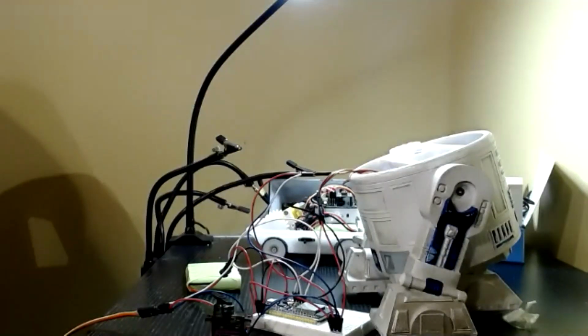Yeah, I've got a quick question. When I look up on Amazon, I see different variations of the ESP32. I see an ESP32S and an ESP32 CAM. What's the difference? What are we going for? Is it just strictly ESP32? The ESP32 is the main core chip, and then the ones that I got were dev boards. Now the pinouts, whereas your Arduino seem to have standard pinouts, and again, anybody who knows better just jump in, there doesn't seem to be the same standards on the ESP32s. But all I think it means is that you just have to make sure that you choose the relevant pins for your particular ESP32. Capabilities are still the same.